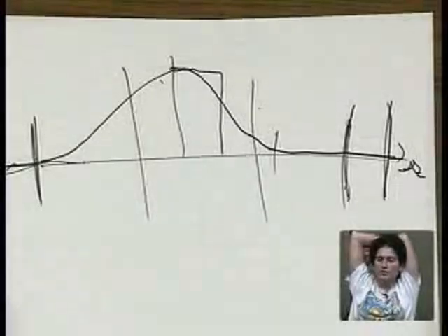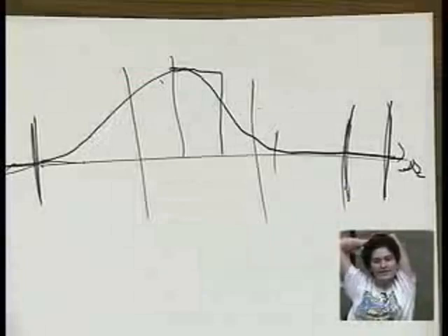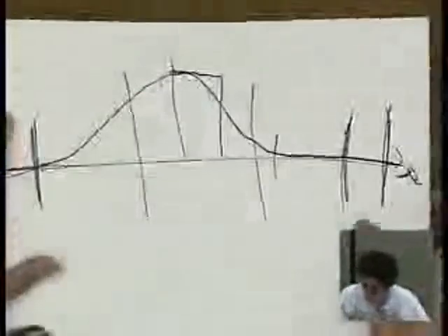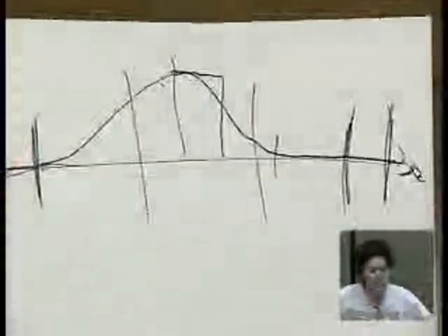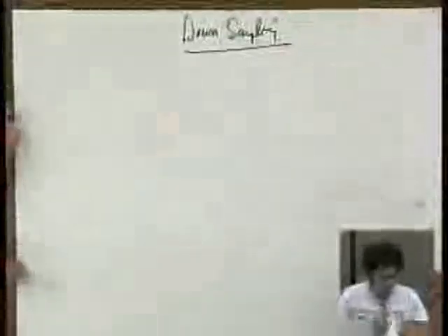So they're trying to produce sort of a 4 kilohertz type version of things. And if the going gets really tough, if the channel becomes bad and the signal is not getting through, then they lower the sampling rate and they lower the bit rate and they adapt to the condition of the channel. Just wanted you to have some data points of what are some typical sampling rates people use in real life. Okay, so let's talk about downsampling.